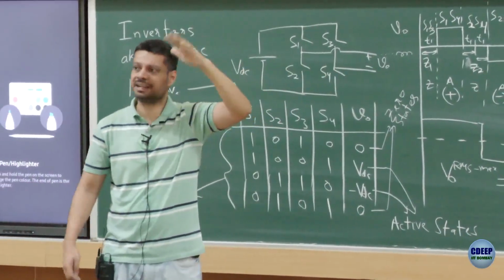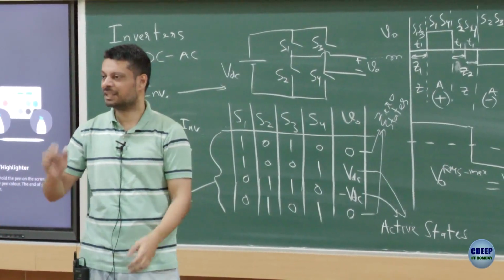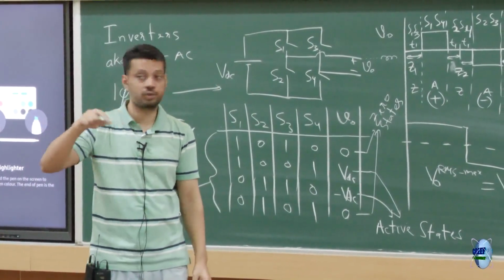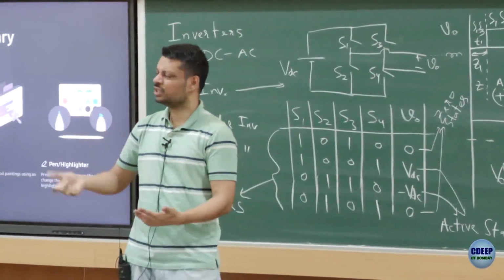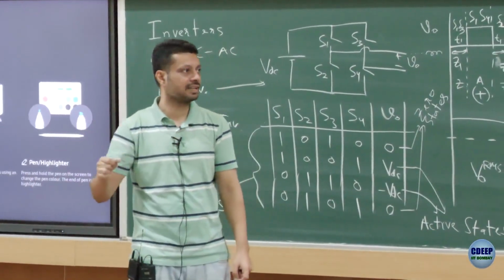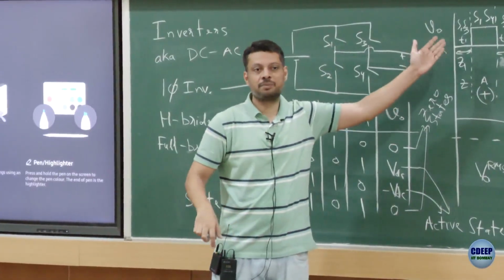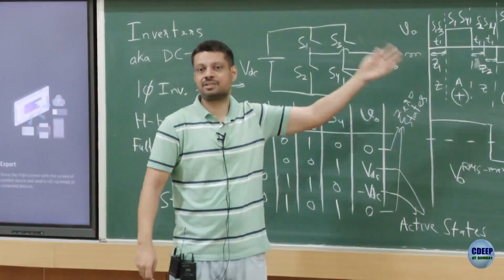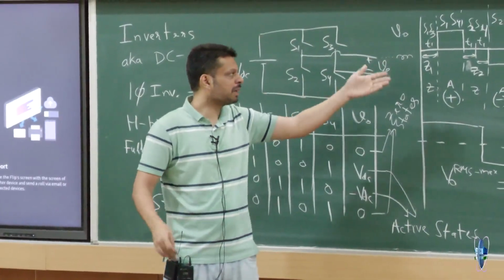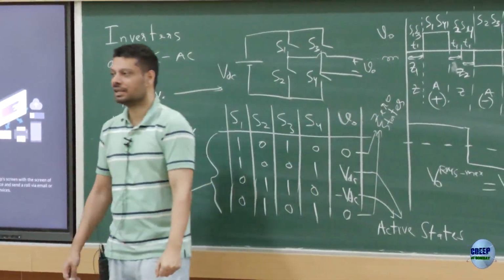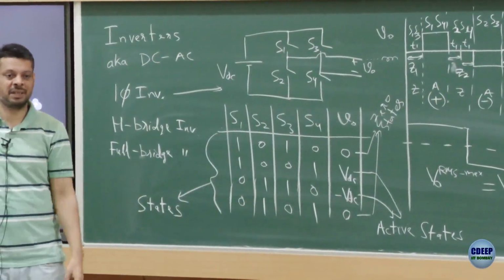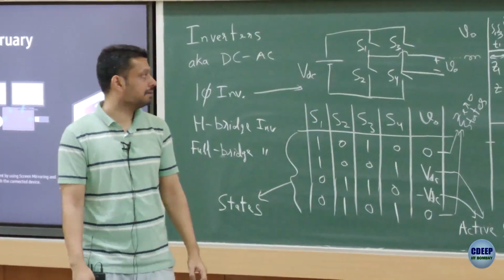You connect it to the fan, it works, it rotates, of course. There's a sound. It's not only the sound, internally there is a torque oscillation also happening. You are losing efficiency, your torque is jerky, so you don't like it. So the objective is to minimize as many harmonics as possible. At least, without putting much effort, we can eliminate the even harmonics just by making it symmetric. That is the simplest thing you can do without putting too much effort.